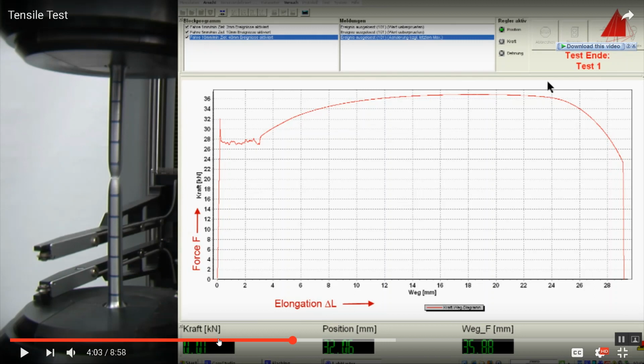This means that this force, when applied on this material with this shape, is only working in the elastic zone. We are still in the elastic zone. So what's the elastic zone? When you apply a force on the material and then remove this force, the material will return again to its original place, to its original shape. So, no change in the material. You are safe in this zone.